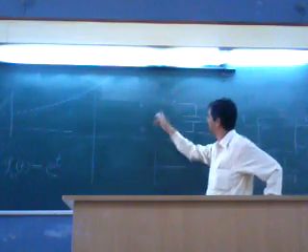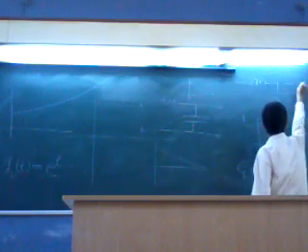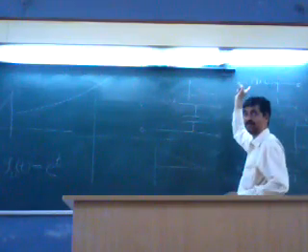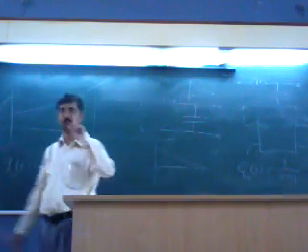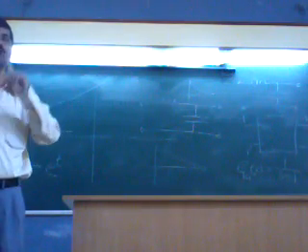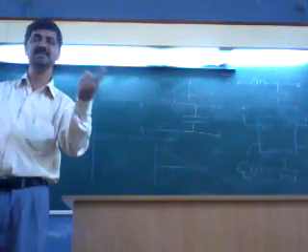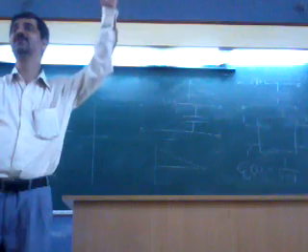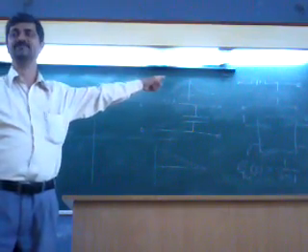Input applied, input has come and gone. Like this, stable system. And input has come and gone, but oscillator system. So three types. Poles in the left half of the s plane, stable system. Poles in the right half of the s plane, unstable system. And poles neither in the left half nor in the right half, but on the vertical axis, the imaginary axis, in that case, oscillator system.